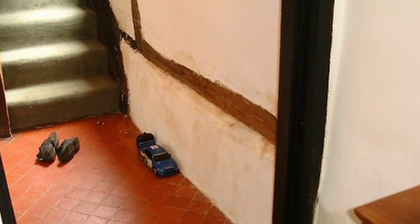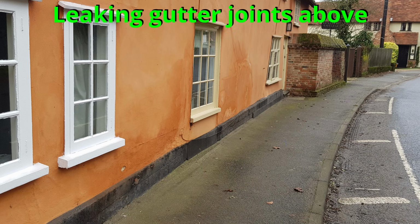Staining. Look for stains. We've already talked about using a moisture meter. I'm not saying don't use one. I'm saying if you see a stain and you think, is it damp, is it not? Then this might be useful, not in identifying whether it's wet or not, but identifying whether there's a real difference between an area of wall or an area of timber that hasn't got a stain and an area that has got a stain. So you're just trying to get that differentiation. Then you have to start saying to yourself, well, have I got a leak somewhere? Have I got water penetrating? What's going on? Is there water there?